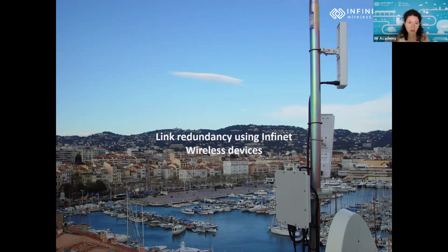We have another question. We are asked if for the scenario where one link is used for upload and the secondary link is used for downlink, this means that if more capacity is needed, we can apply this scenario. Yes, this scenario of a full duplex can be used to increase the capacity, and you separate the uplink transmission from the downlink transmission on a different path. But you are using both links at the same time, so you have an increasing capacity. It is the 2+0 configuration, okay? You can choose either link aggregation or full duplex in order to increase the capacity. The difference is that for link aggregation without full duplex, the uplink and downlink directions will take turns in transmission.